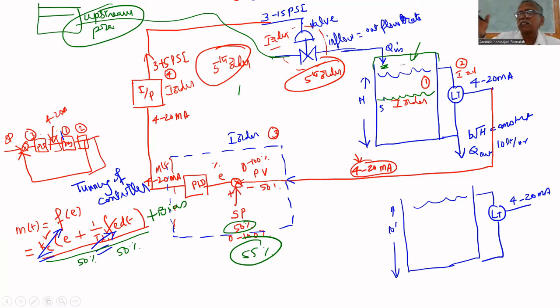So, there are so many disturbances, depending upon the design. Those disturbances will be managed by the controller. Suppose the density of this liquid, don't think of it as water. Let us assume that it is some chemical liquid. Its density may change from today, tomorrow, day after tomorrow. Depending upon the density, outflow rate will change. Small change, but after a long time, there will be a large change in level. Let us assume that density is decreased. That's why outflow rate is increased, a small amount. But after 5 hours, level will be drastically reduced.